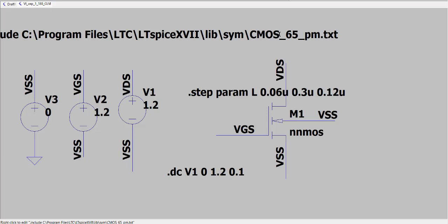Okay. I just wanted to show you the channel length modulation. So 1 plus lambda VDS, right? And lambda is inversely proportional to length. So if length increases, lambda will decrease, and 1 plus lambda VDS will decrease. And my current will be more towards the constant current, which is the actual value, because 1 plus lambda VDS is now small, right?